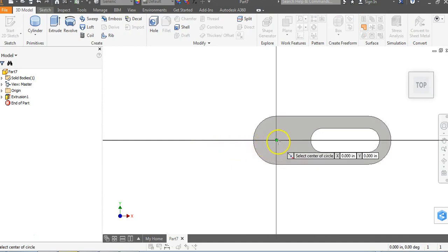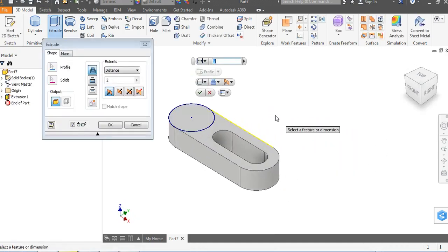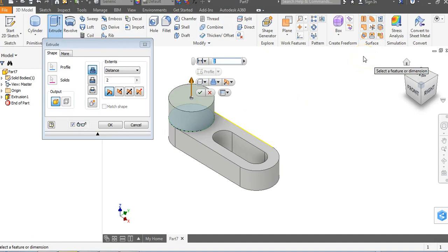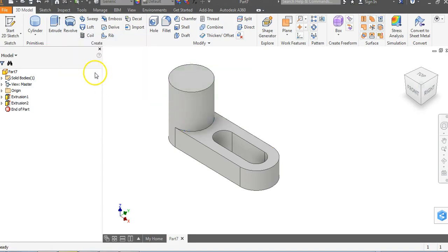We're going to click on this object, and all we have to do now is just click on our center point of our arc over here. I'm going to click, and I'm going to snap out. As soon as I see that 2 show up, I'm going to click, and it's going to rotate for me, and it's automatically going to go to creating a cylinder. So our height we said was 4. I'm going to highlight the 2 and put in a 4, and hit enter.